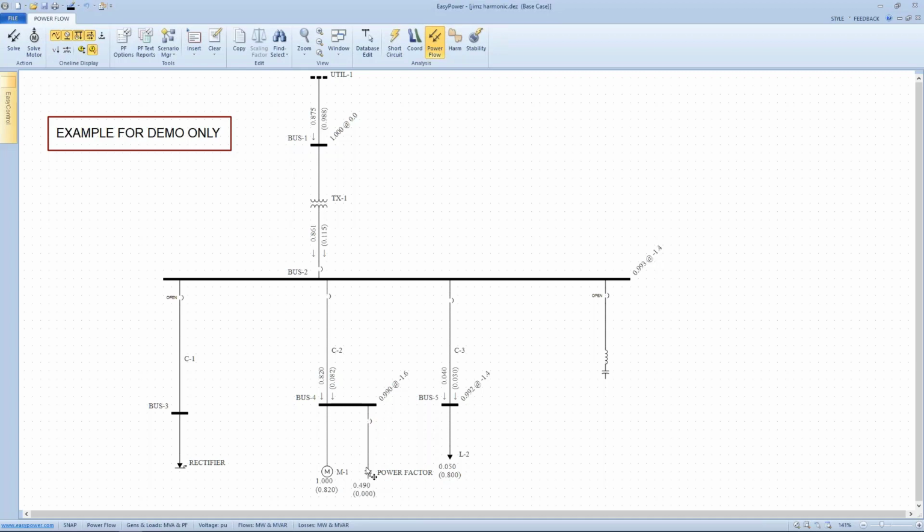So as I bring on this capacitor bank, what I see is my voltage is now brought up to 0.99 per unit. My reactive power demand is cut by 90%. I can see that my utility power factor has gone up to 0.98, and the utility company will be much happier. I get a much more efficient use of the motor now, and everybody's a happy camper.